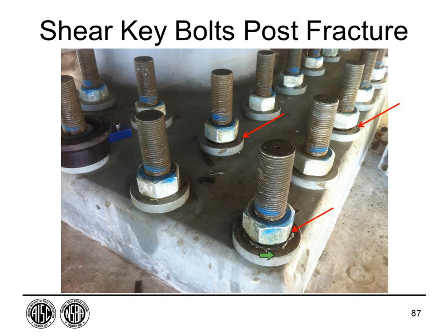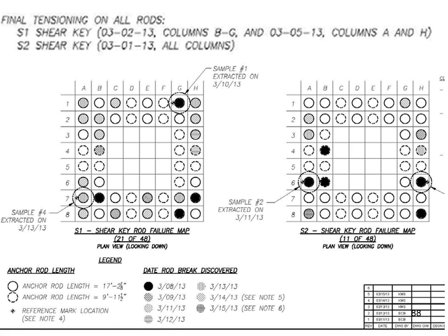They were stressed not using turn of the nut, they were stressed using a hydraulic jacking system. So we have here 3 nuts showing a rather unusual situation. These are completely loose, and so they're an indication that we've had a fracture. And on close inspection, there were a lot of broken bolts or rods.